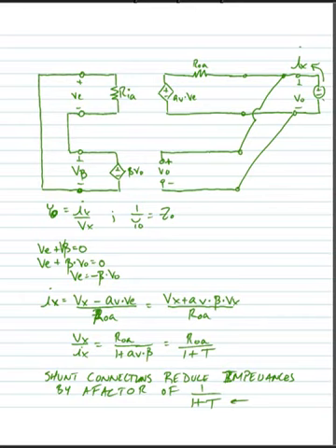So if we want to figure out what happens to the impedance of a circuit, we can find the forward resistance first, and then, if we know that we have a shunt connection, divide that resistance by 1 plus the loop gain. Now in this case what we see is we wanted a voltage output, and we know that for a voltage output we'd like to have a smaller impedance at the output, and so this reduction in output resistance helps us and makes our voltage output better.